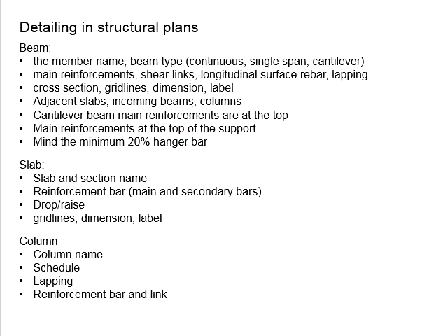First, you need to clearly indicate the name of the beam, and this name of the beam will be on the basis of your structural key plan. It must be in line so that the contractor is able to locate which beam it is referring to in your structural key plan. Your detailing also gives an idea what type of beam it is.